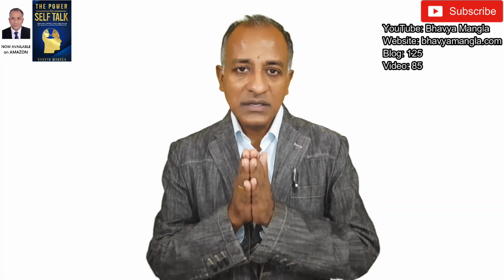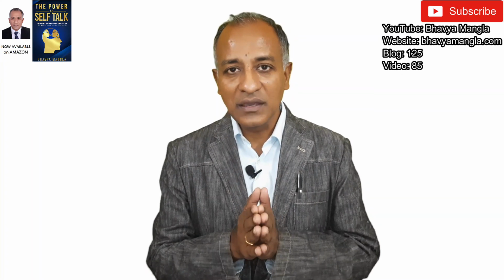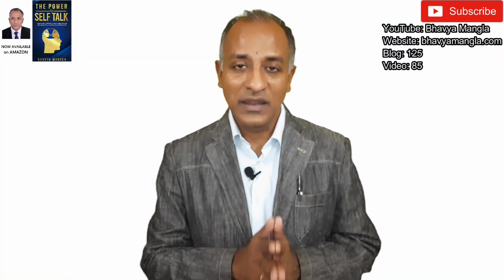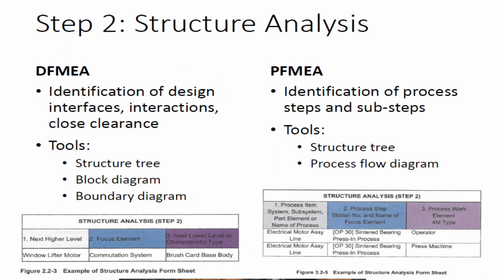One very important thing is that in case we are missing something during the structure analysis, surely it will get missed in the function analysis also. So we should be very careful to identify all the possible things in the structure analysis. If I do a summary with respect to structure analysis, when we talk about DFMEA, the intent is to use a block diagram, and here we are talking about 3 key things: next higher level, focus element, and next lower level.